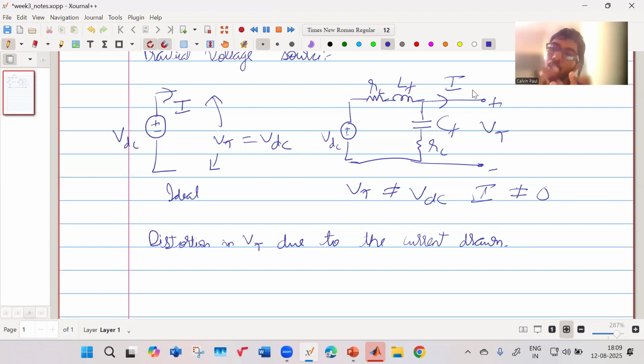So a huge inrush current is being drawn. When the current is very high, this voltage will go down. And when this voltage goes down, the tube light or other things will go dim. The fan speed will reduce, the fan might even stop. All these will happen. So that is a practical thing which we see.